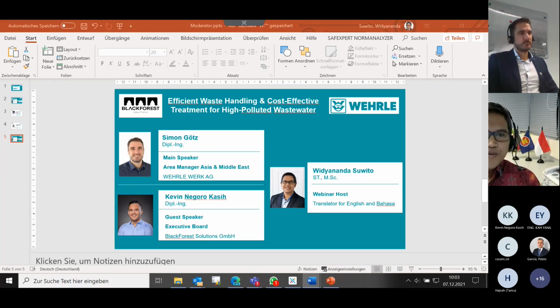Okay, the second question is coming from Mrs. Hajra. Would you please explain more about the energy consumption of MBR biomembrane technology, Mr. Simon? Okay, the energy consumption of a biomembrane is slightly higher than, for example, a submerged plant. Why? Because we have those booster pumps.